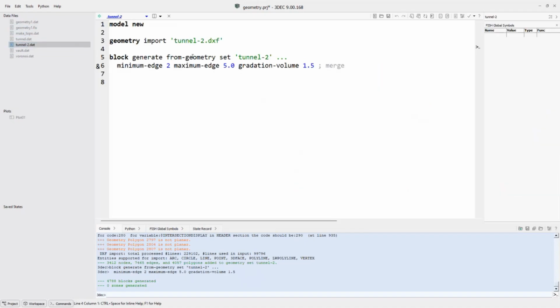Okay, in the original case, we created tetrahedral blocks, which you would probably want to join together. This is fine because if you have blocks, you can then do further cuts, because often you might import a geometry or create these blocks and then want to cut a joint set on top of that. If you don't want to do any more cutting, you can turn these blocks into zones as you import them.